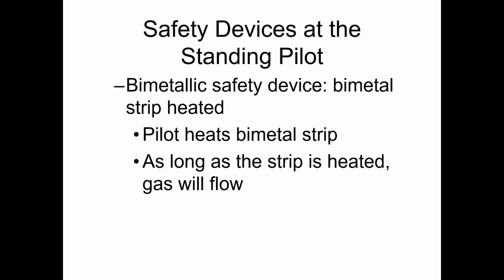It doesn't have to be right in the middle of it. It can be just a quick little disc or a little bimetal strip, basically. And those don't have to be right in the middle of the flame. So building up soot on them really doesn't become as much of a factor as it does for our other ones. So this has got that as a major advantage for it. But basically, as long as that's got heat going, there will be gas flowing. That's the whole thing. As long as there's heat, gas will continue to flow to the pilot.